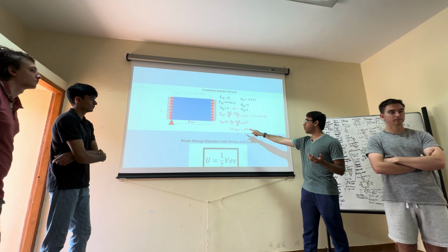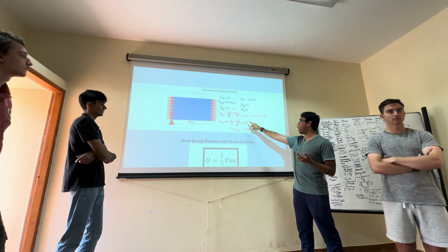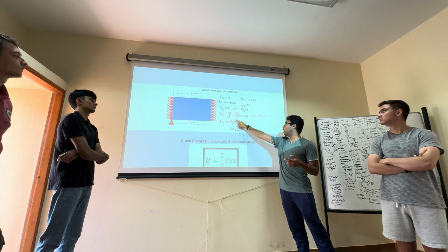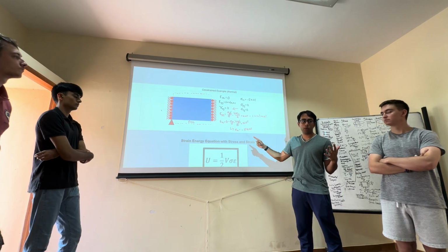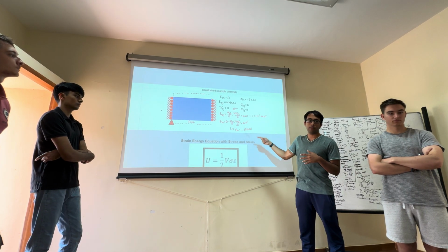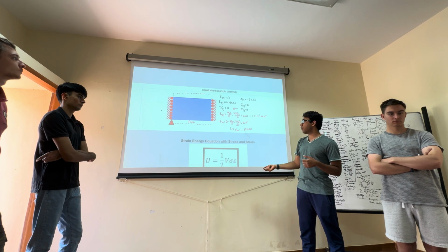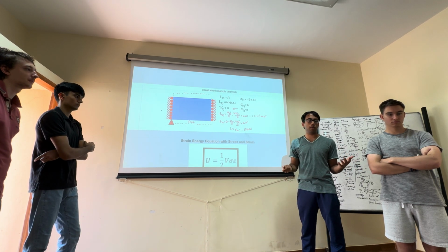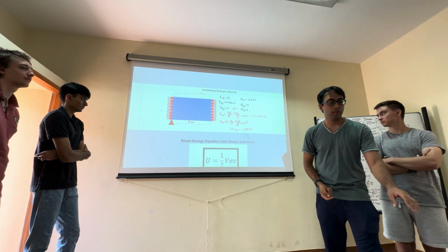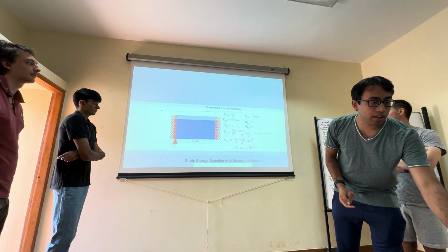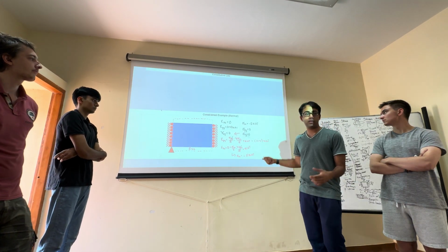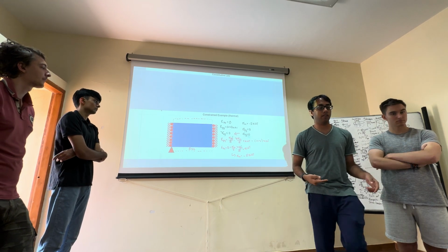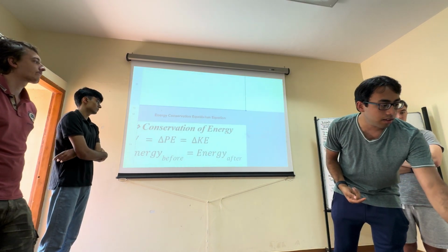For strain in the y direction, the mechanical strain is going to have no stress, so the remainder of the equation gives us whatever the strain will be in y. Using this, we can also derive what the stress in the x will be based on whatever constraints we have. You'll notice that the answer here is negative because when we're expanding outwards, the reacting forces are pressing in on us. So it's a compressive stress that's being applied.